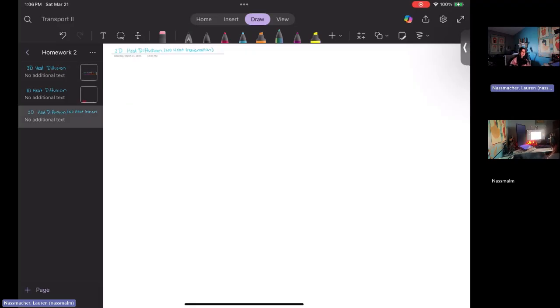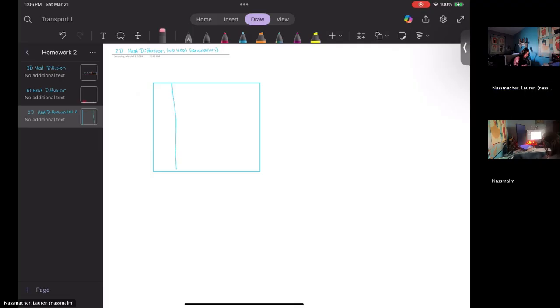The first thing I want to start by doing is visualizing the problem. You're going to want to create a grid to visualize that two-dimensional heat diffusion because you're going to have two dimensions, our x and our y direction. And those x and y directions, we can split this grid into 4 columns and 4 rows, right?